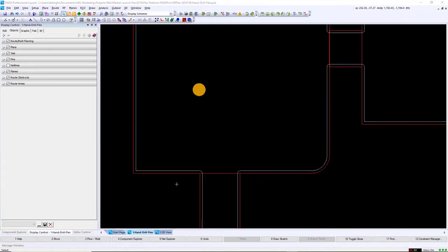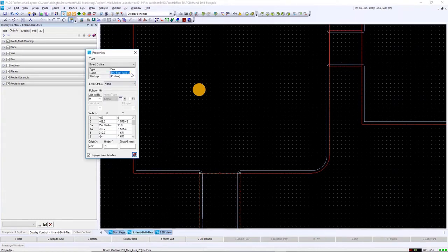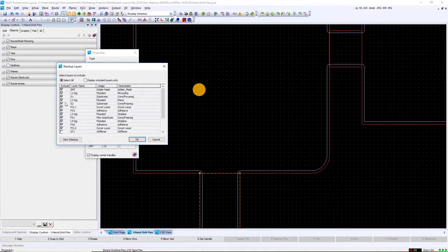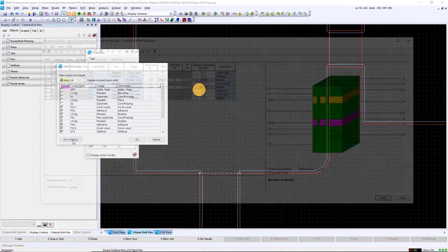One of the most important features of a modern ECAD tool in regards to flex design automation is assigning intelligent stack-up information to each region of the board. Here we will double-click the LCD display flex region, give it a label, and then choose the layers that will be used to manufacture this section. This is a section that will connect to the external board and require a different stack-up definition than region 2 due to the added stiffener.